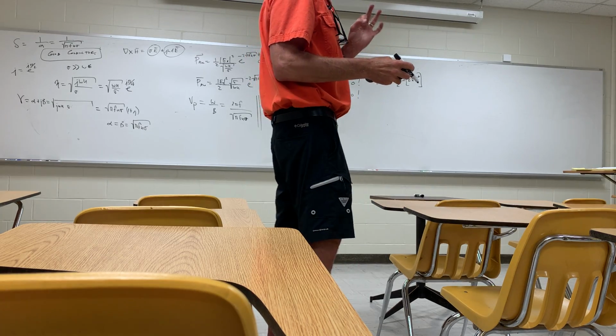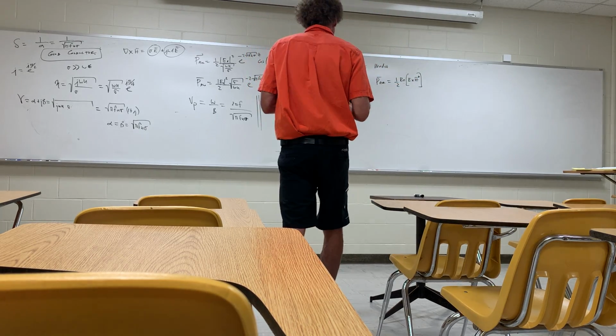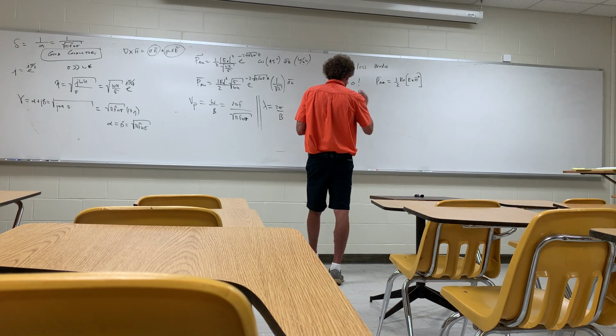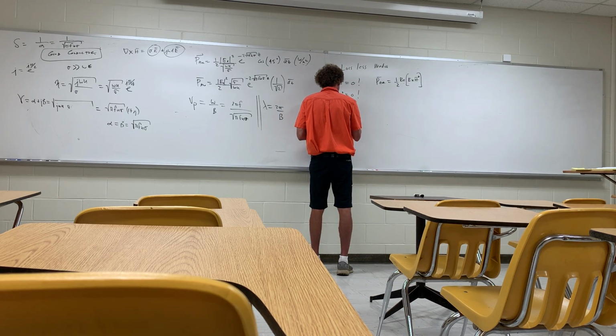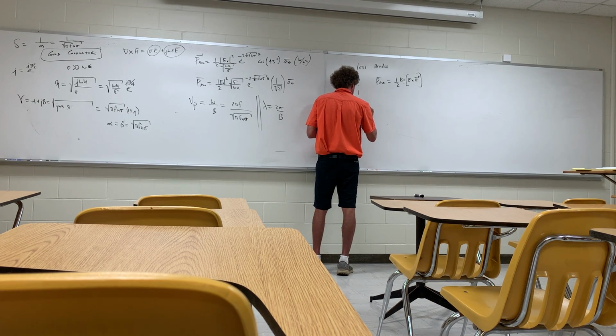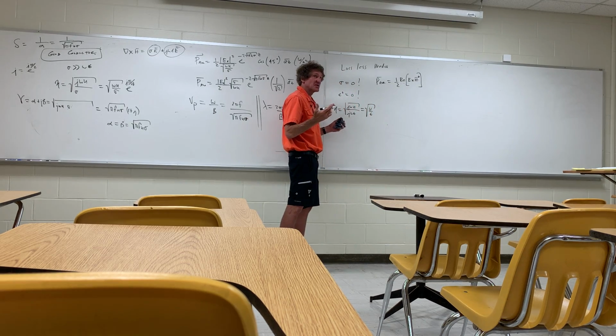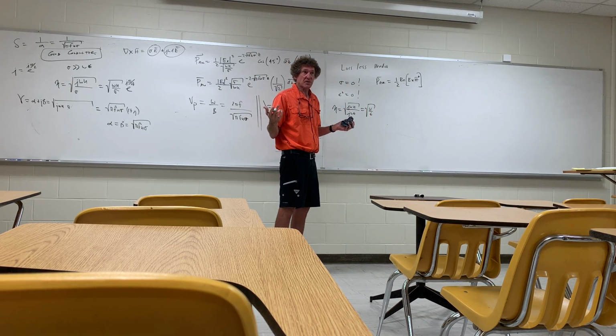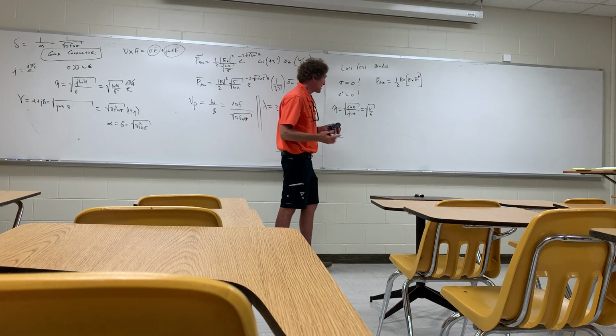The angle associated with eta, let me just tell you what I'm talking about. If it's lossless, then eta itself is equal to the square root of j omega mu over sigma plus j omega epsilon. But because sigma is 0, it's over j omega epsilon. So it's really square root of mu over epsilon. So the angle here is just 0, right? It's strictly real. Do you all agree with that? It's e to the 0.